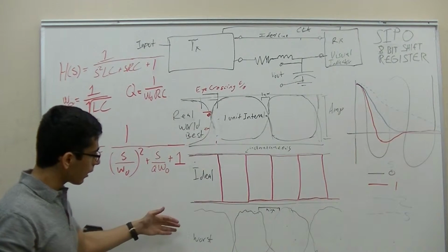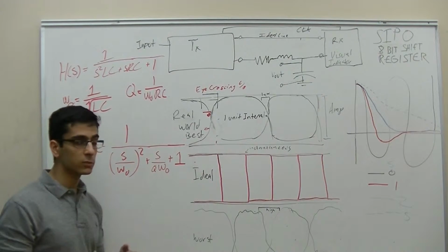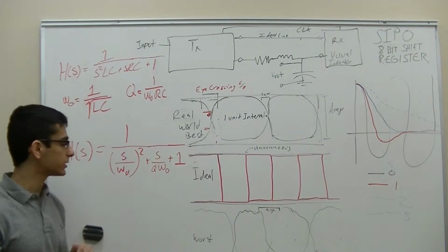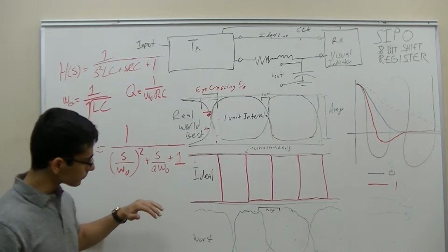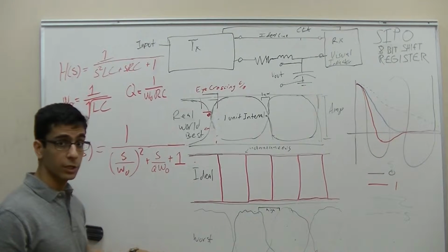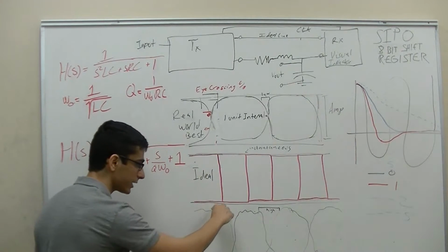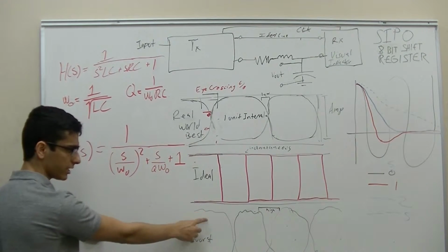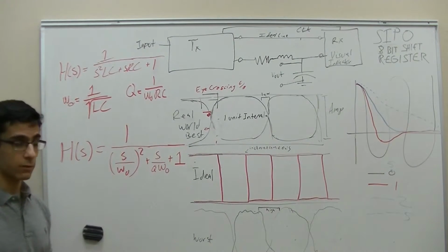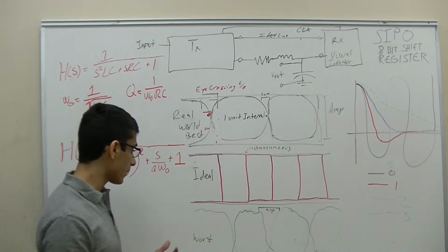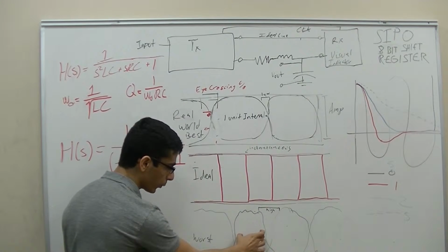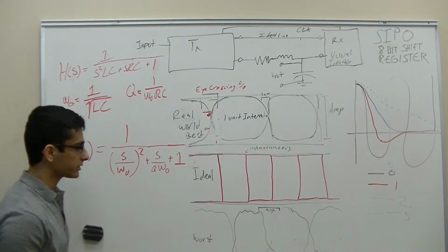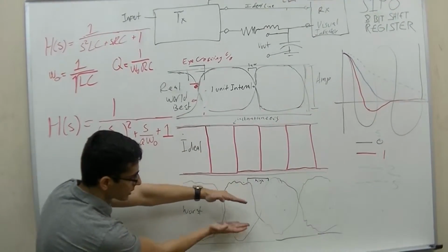Now, there's also a worst case scenario for this, and this will depend on the components that we have and their parasitics from the capacitors and the inductors. If you have a low damping ratio, you're going to have high ringing that you'll see as the eye diagram starts to curve. You see it right there, and here, and in various other parts. Also, from a low Q and a high parasitic amount in your signal, you'll see that the eye window is small, the window height shrinks.